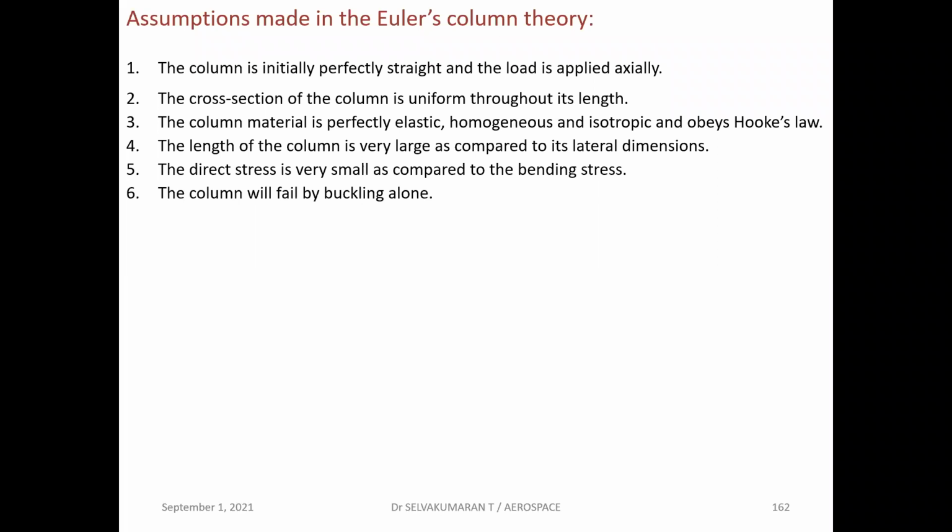The column will fail by buckling alone. We assume that the column fails only by buckling. The self-weight of the column is neglected or negligible. So we are not considering the weight of the column during our calculation. We consider only the external load, that is the axial compressive load applied to our column. Okay, self-weight of the column is neglected.